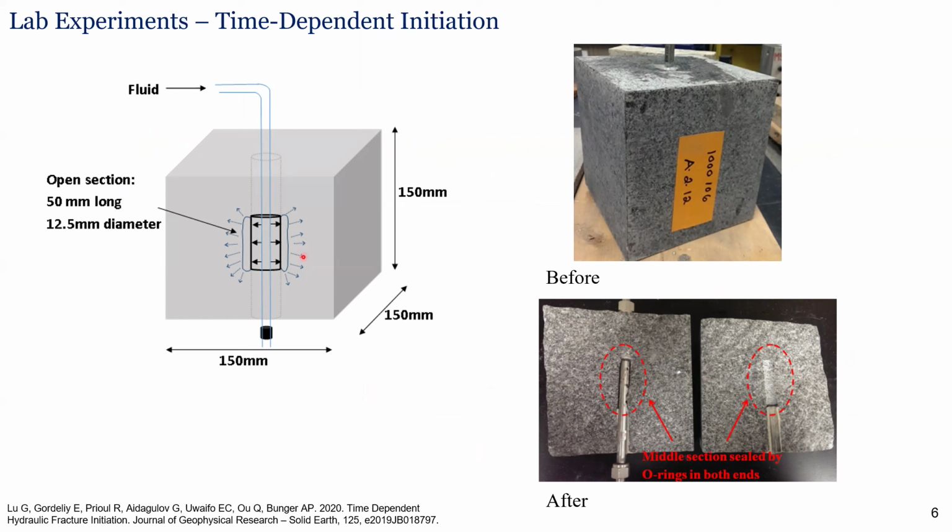We were funded by Schlumberger for this work originally, looking at this problem of what do you do when you're fracturing for stress testing from packers, where the packers have a limitation and sometimes they can't achieve breakdown. But there's this kind of field experience that says, well, if you hold for a little while, maybe you can eventually get initiation of a hydraulic fracture.